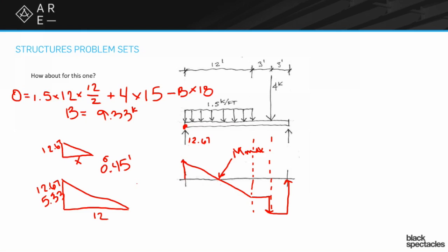And so that tells us our basic question, which was, where is the highest amount of moment? Correct. And we figured that out through a combination of using the shear diagram, understanding kind of what the shear diagram was telling us, and then doing a quick, fast graphic version of helping us understand where exactly that point of crossing is. But we also could have done a moment diagram. We could have done a sum of moments and then figured out distances. There's a series of other things we could start to figure out as well.